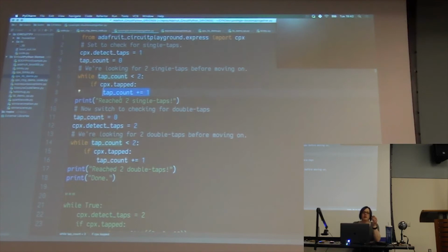So the accelerometer on here has an interrupt pin, which sort of works. Interrupts as a whole are not supported yet in CircuitPython. It's not a huge priority because it's a much lower level thing, and right now we're working on building the higher level side of things. However, there is an interrupt pin on these chips. It is connected, and it can be used.